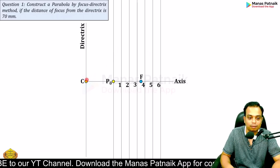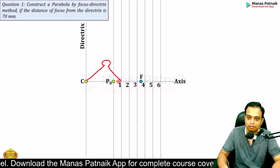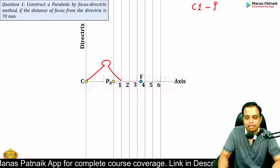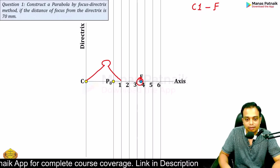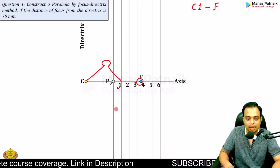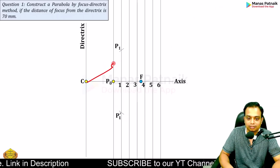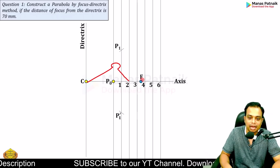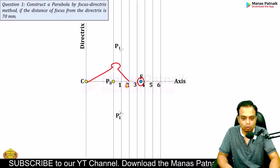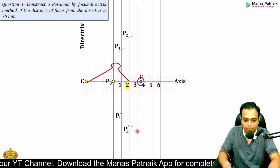We are going to make use of a compass. So with C1 as the radius, listen to this, with C1 as the radius, and now with focus as the center, you need to make an arc on this vertical line passing through 1, above and below. Simple, done. Now with C2 as the radius and with F as the center, and on this vertical line passing through 2, you need to make another arc, P2 and P2 dash.